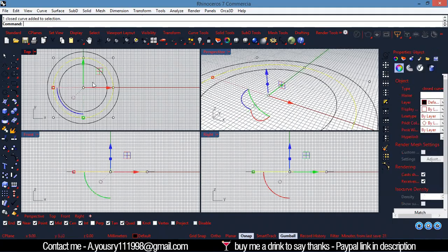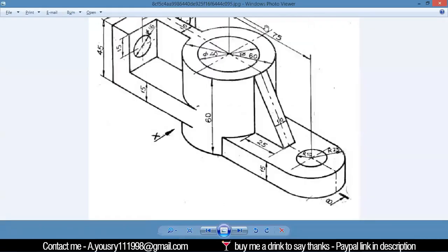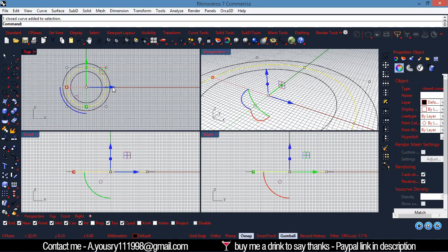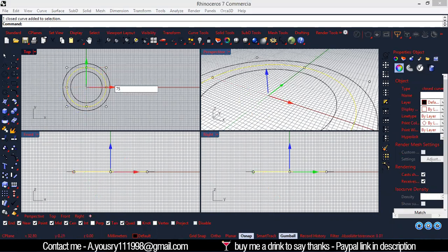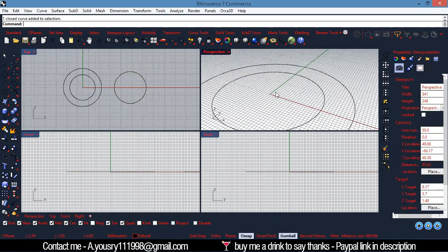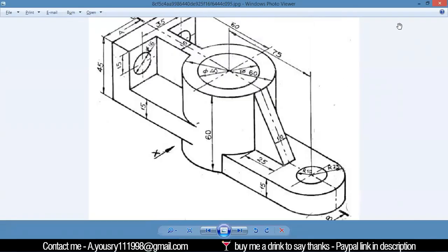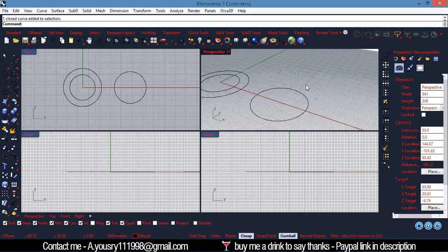And the other, let's move that to 75 from the center. Okay, so I'll move that. I'll tap here and just type 75. Okay, here we go. All right, so if I want to do the other circle here, which is the 10 millimeters, I go to the last command and just come here to get the center and make sure that my O snap is on and the center object snap is checked. So I'll put here and type 10.